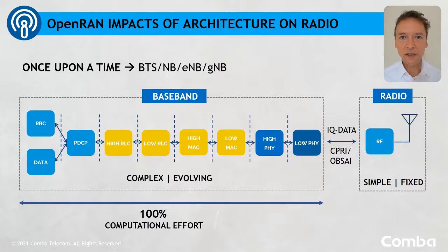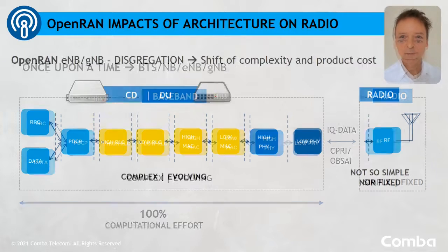This is a traditional view of a RAN. Life was simple. This model has been used for a long time. It made sense in the past allocating variable parts of the standard to one location, the baseband unit. Complexity was done with software and accelerators. Radio function was a relatively fixed part that only changed when stepping waveform standards from UMTS to LTE to NR.